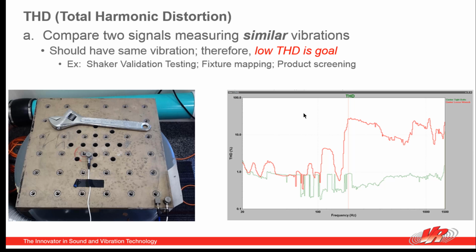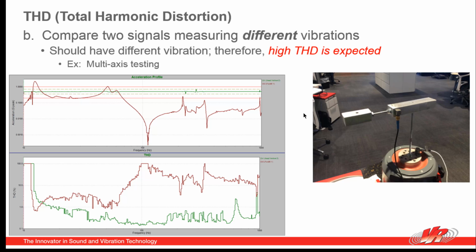We also try to test with multi-axis vibration. We set up some rather strange configurations just to test out our system to see what we could get. And here is a triax accelerometer at the end of this mass, and you would expect this rod to vibrate up and down, and the whole system should vibrate up and down.